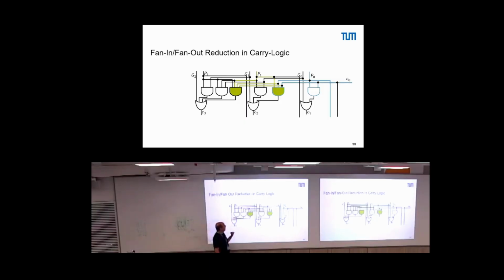And I start here with this fan-in, which is here an AND gate, driven by this, this, and this. And what you may immediately see is that these three wires here are actually already there. We already computed them. So if we anyway have to split maybe the NAND gate or the AND gate, why not using just this output, right? Because this is something we have already computed.